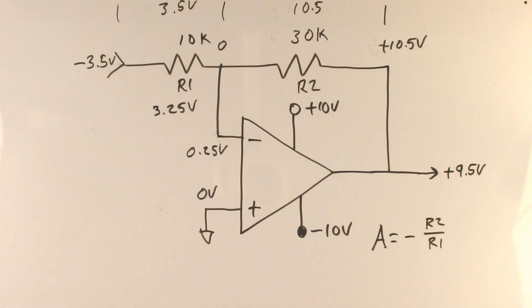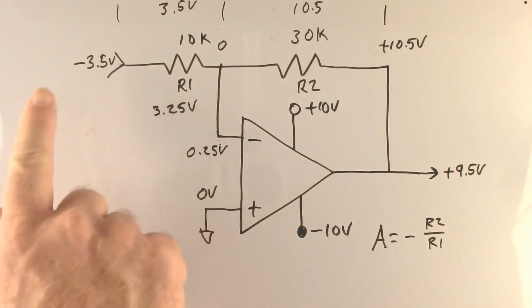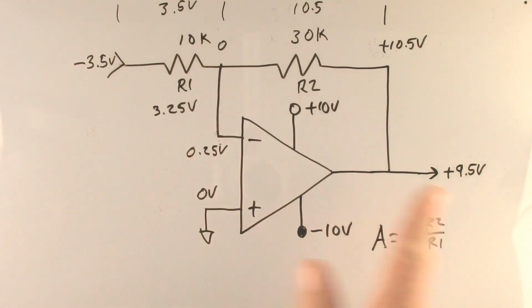Well, same things we could with the non-inverting amplifier. We could limit our input. If we have a lower input voltage, then we'll have a lower output voltage. So just say, well, the input's too high, we're overdriving it. The circuit doesn't change, we're just outside the parameters. We could lower the gain by keeping the resistor ratio lower, and then we could accept this voltage, but we'd have a lower output voltage, but we would have an acceptable, usable circuit.